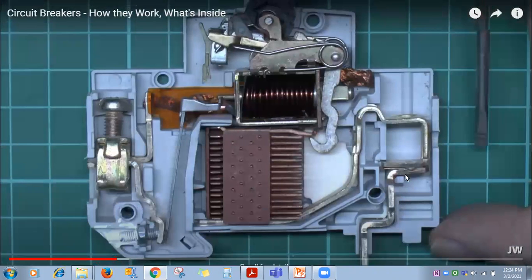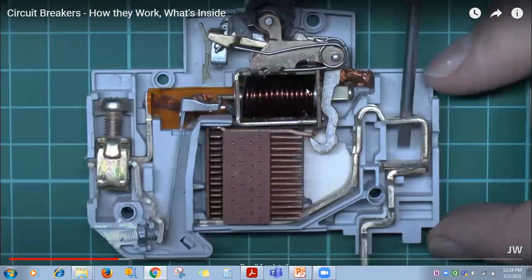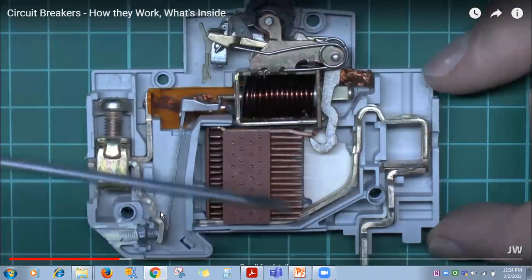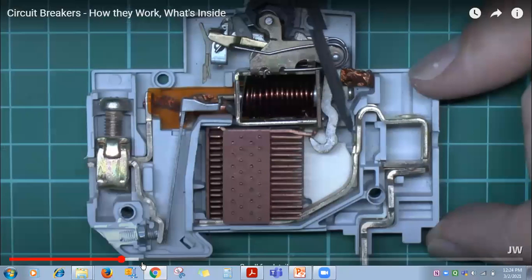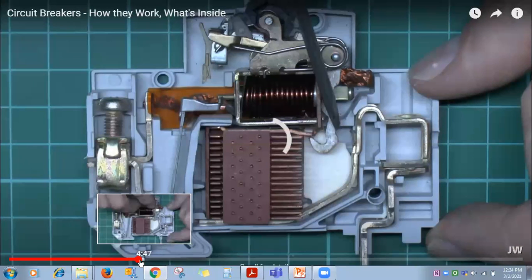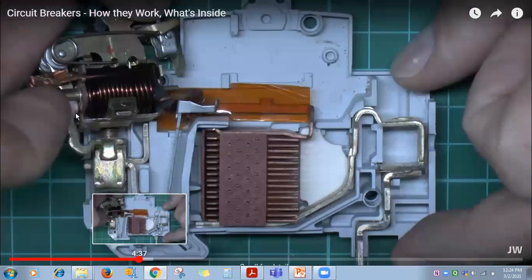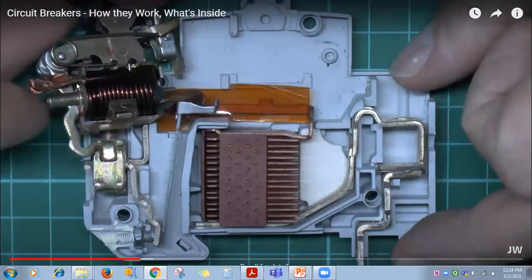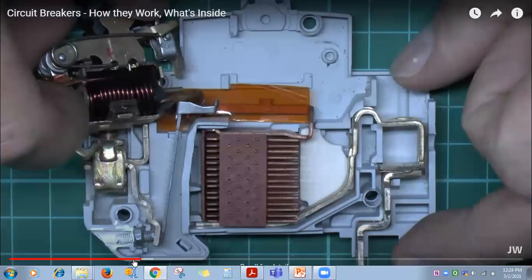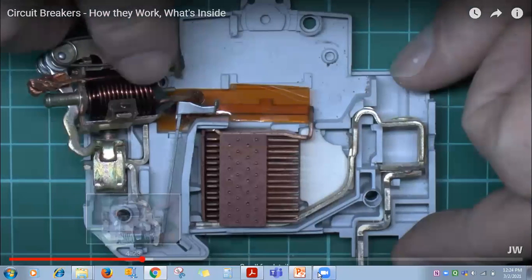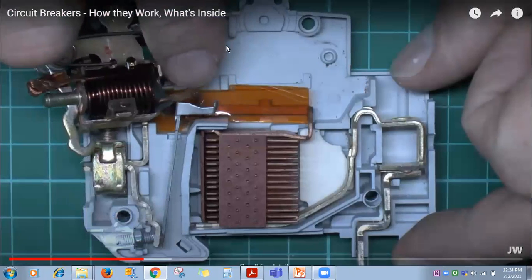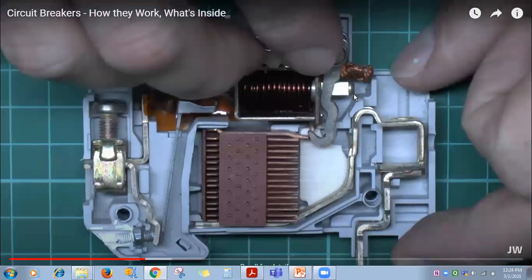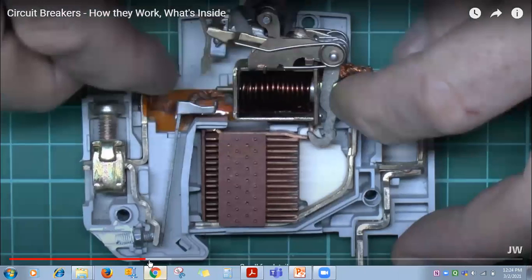This one is the fixed contact, this one is the movable contact, then solenoid, bimetallic strip, arc chambers, and live contact. Here, see, this is the latch, and a plunger spring arrangement is there inside. The solenoid, in case of short circuit, makes the circuit open. The switch comes to the off position.